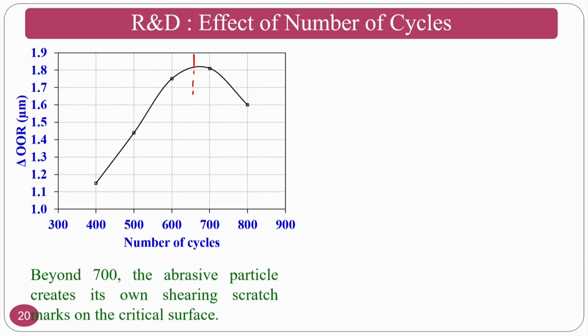If the viscosity goes down, the abrasive holding ability, what we call the grade in the grinding process, will change from hard grade to soft grade. In those circumstances, the abrasive particle will only slide on the surface rather than finish it.